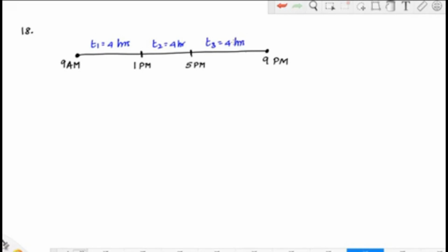So whenever you are having two or more than two rainfalls occurring in succession one after the other with different intensities, I1, I2, I3, with respect to this you will get P1, P2, P3. So with respect to this, you will get three runoff values R1, R2, and R3. So whenever there are two or more than two rainfalls of same duration occurring in succession, you have to go for convolution method.